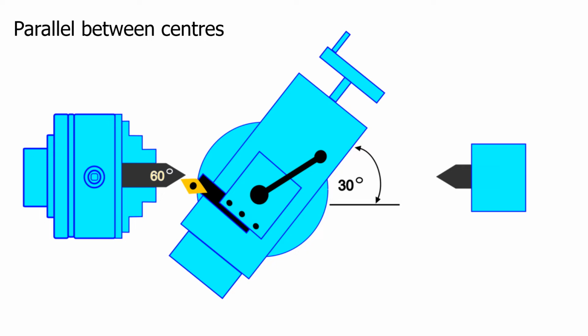I could use either a faceplate and a center, but in this case I'll be using a chuck with a mild steel center. I prefer this method as it gives me a chance to skim the taper and ensure that I'm running concentrically with the chuck.